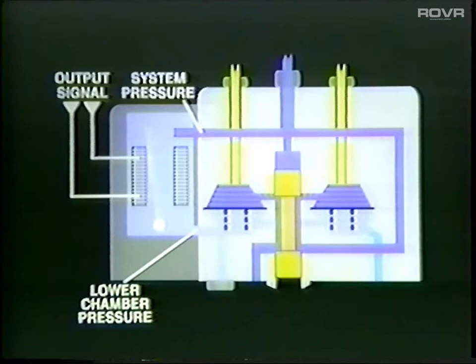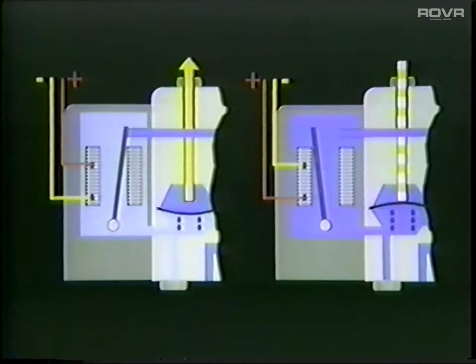The principle of controlling fuel delivery by regulating the pressure differential between upper and lower chamber is explained in the Education for Excellence program covering the lambda oxygen sensing system, so we will not repeat the explanation here. Depending on the direction of current flow and the intensity, the valve will bend towards or away from the fuel inlet orifice, thereby regulating the amount of pressure in the lower chamber of the fuel distributor. The resulting change in lower chamber pressure deflects the fuel distributor diaphragm, and more or less fuel is delivered to the engine as required.